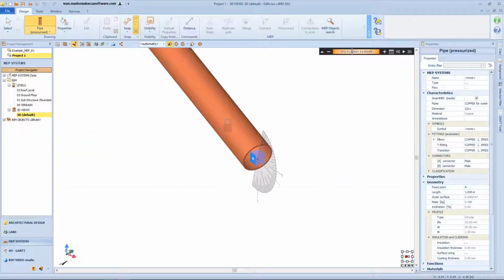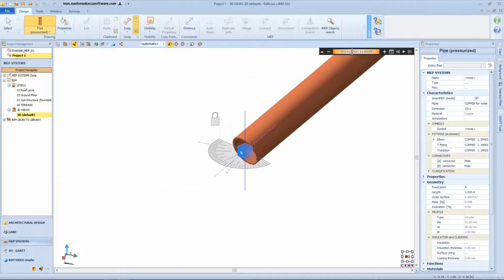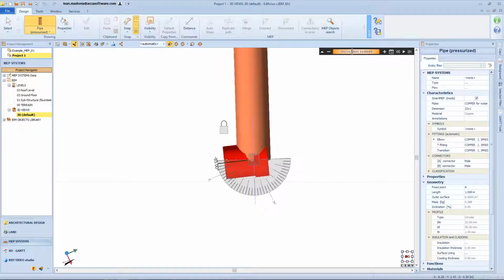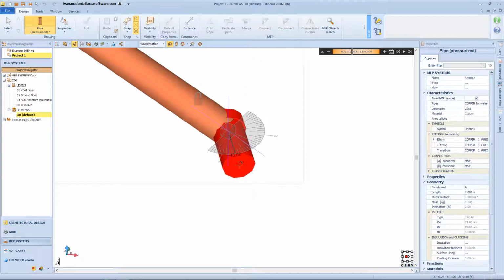The protractor that appears by default allows you to trace the pipe in a plane orthogonal to the section. Therefore, if the pipe does not lie on a horizontal plane, the goniometer will not coincide with the default directional cubes. Moreover, using the protractor, the pipe can be traced according to an angle that varies from 0 degrees to plus or minus 90 degrees. The angle chosen during this phase will be used to generate the curve automatically, therefore it is not possible to model curves with a curvature angle greater than 90 degrees with the protractor.